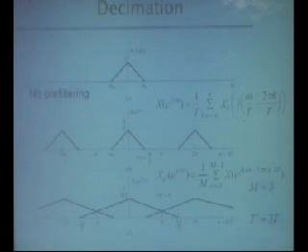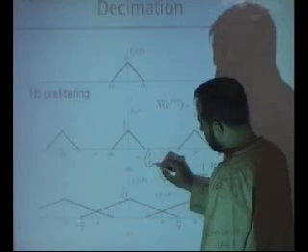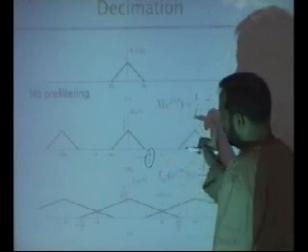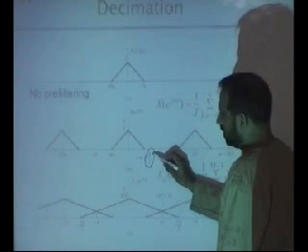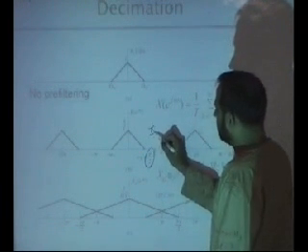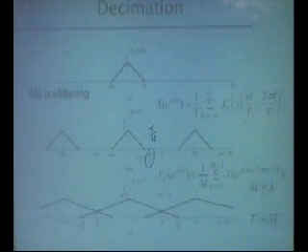We must always make sure that, if you want to throw away samples, there is just one criterion: look at the highest digital frequency. The highest digital frequency must be less than pi over M, where M is the number by which you intend to downsample.